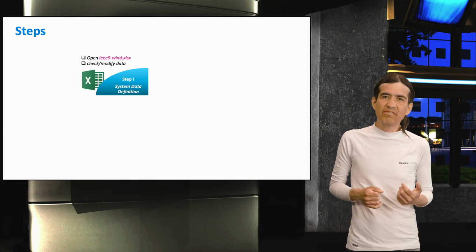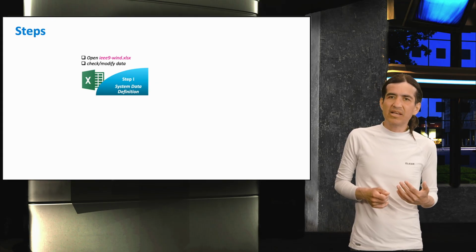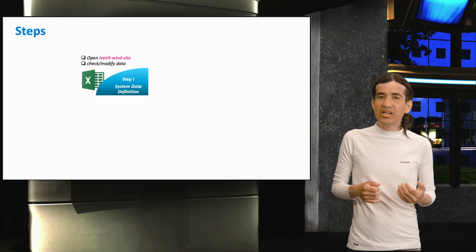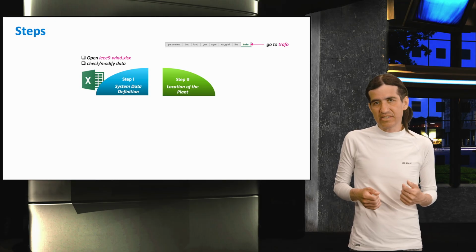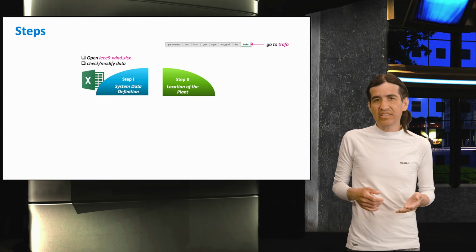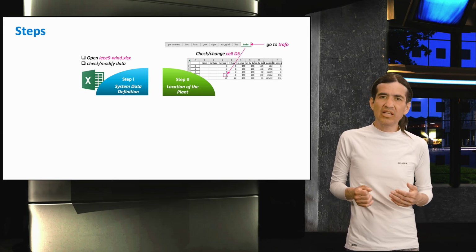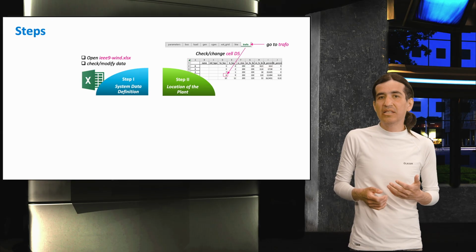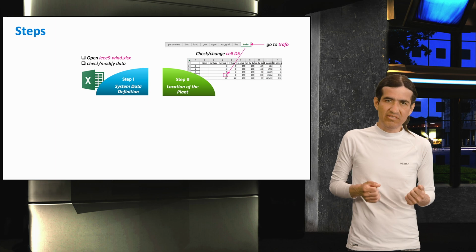Hence, the data of the modified version of the IEEE 9-bus system is included in the file named IEEE 9 Wind XLS. You can change the data of the Excel file to ensure that Panda Power considers any desired modification. For instance, the Excel sheet named Trafo contains the data related to transformers. For illustrative purposes, let's consider that the user wishes to change the location of the interconnection point of the wind power plant. This can be done by changing the index or bus number given in cell D5.